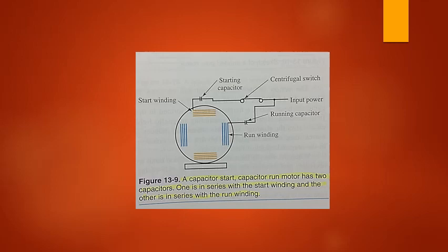A repulsion induction motor. A repulsion induction motor resembles a DC motor because it also has a commutator and brushes. However, in the repulsion induction motor, the brushes are connected to each other rather than to the source of power. The brushes are arranged so that only selected armature coils are closed to form complete circuits at any given time. The currents induced by transformer action in the rotor windings are displaced by the shorting brushes. Poles are created that oppose the stator poles. Rotation is started by repulsion.